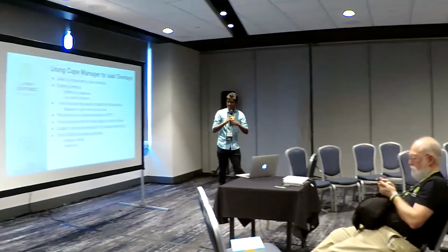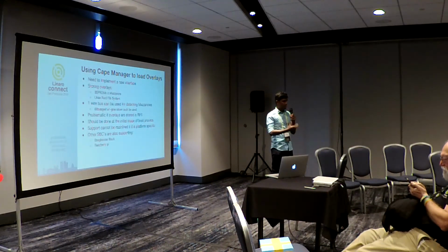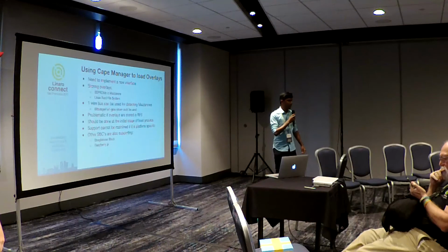Thanks. In order to demonstrate these two things, I have ported U-Boot for merging the overlays on our DragonBoard 410c. I have a blog written for that, so please go and check it out. It's in my private Git repository, not in the 96Boards U-Boot repo. I've written detailed instructions on how to load overlays using that. I was using the SD card to store the overlays, and I'm using the uEnv.txt file to mention which overlays we need to use. I also implemented the configfs interface in my personal repo for the Qualcomm kernel. So if you want to check it out, please do. Thank you. That's it.